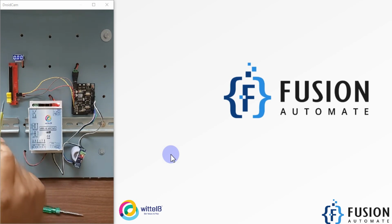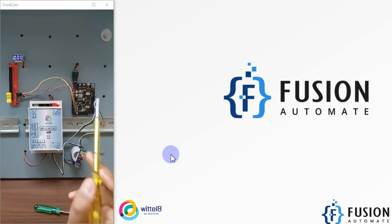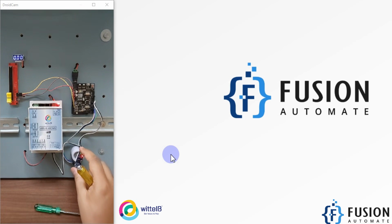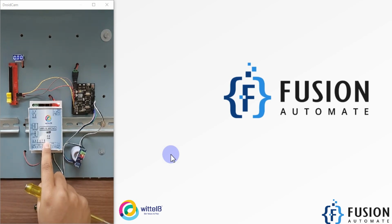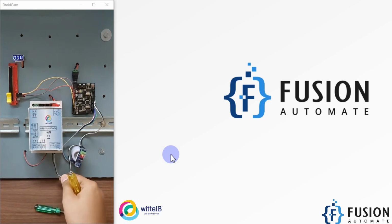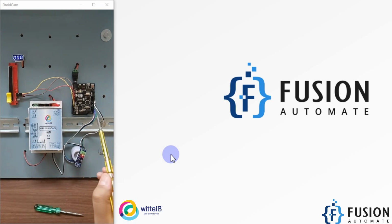As you can see, I have a linear potentiometer here which is connected to Arduino. Arduino is connected with this MAX485 TTL to RS485 converter, and this converter is connected with this Modbus IO card serially. I have connected the two cables, RS485 A and B, to this converter, and this converter is connected to Arduino.